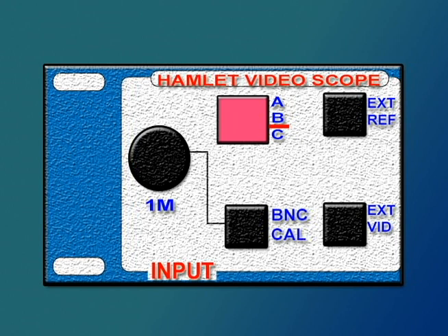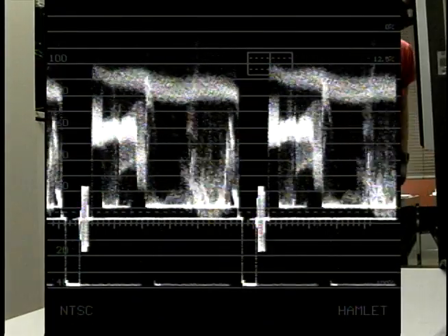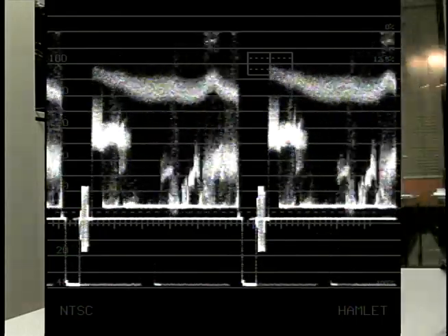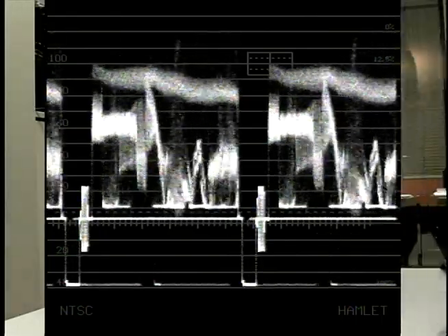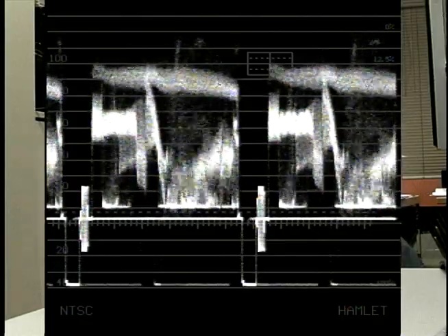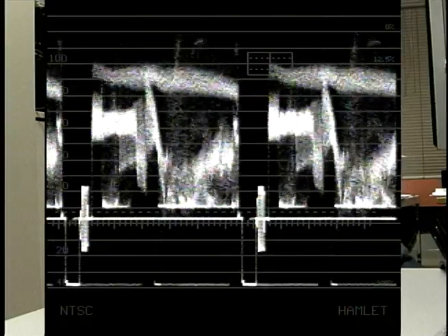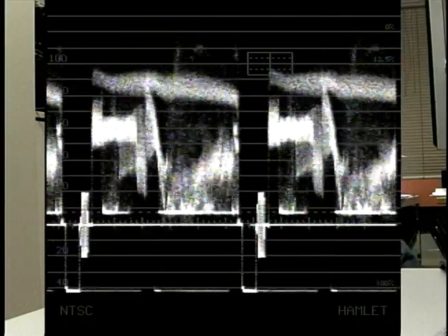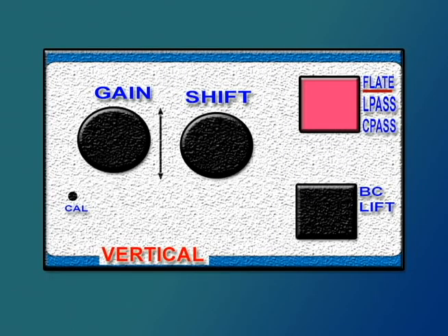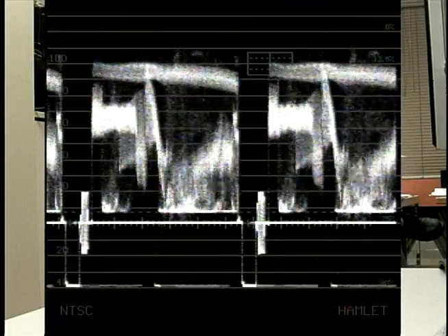Focus the camera on a subject. Make all required camera adjustments, including the setting of white balance. Position the signal from the camera correctly on the waveform monitor display. Blanking level must be on the 0 reference line. On the waveform monitor, set the response control to flat. Observe picture signal levels, including reference black and peak white.